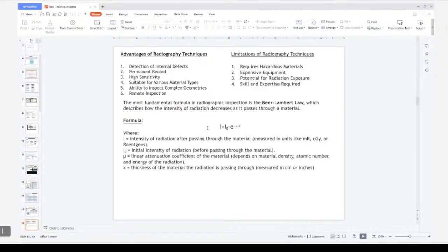In future, X-ray computer tomography will be used because it can help you get a complete view of the component and its defects, and its morphology, the locations, and other factors about the defects very clearly. So all the additive manufacturing companies employ X-ray CT for internal defect detection. This is the only technique available to do internal defect inspection in such cases.